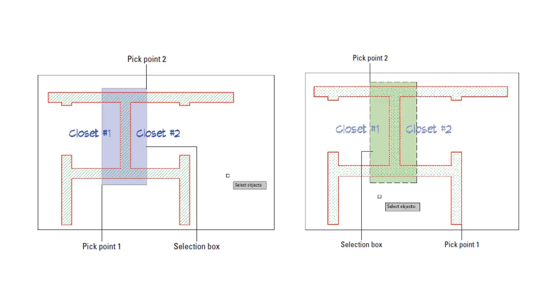Selection boxes left and right. Selecting objects one at a time works great when you want to edit a small number of objects, but many CAD editing tasks involve editing lots of objects. Like most windowed graphics programs, AutoCAD provides a selection window feature for grabbing a bunch of objects in a rectangular area.